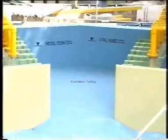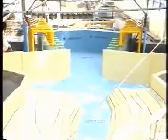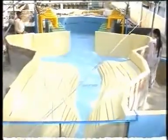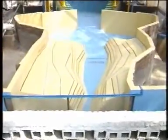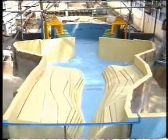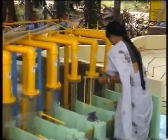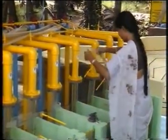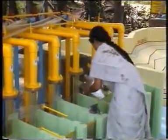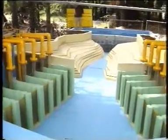Each color represents the contours at 1 meter interval and the lowest elevation is 587. The entrance channel is seen with its natural profile showing the contours marked thereon. You can now see the intermediate slab being introduced in the pump chamber. The model is now ready for the experiments.